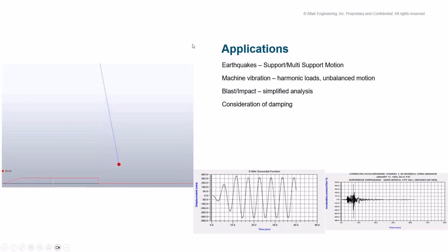And as you can see here, I've got a little video that I played at the beginning. This is actually just a unique example of using time history loading and analysis. In this case, we had a pendulum model, which we were basically pushing to the side and holding it there. There was a bit of oscillation, and then we let it go and watch it swing. This is just a quick snippet from SView to see how that looks. Now, it's important to understand as well that time history loading and the analysis itself must be broken into discrete time steps, and that's something that we're going to be talking about.